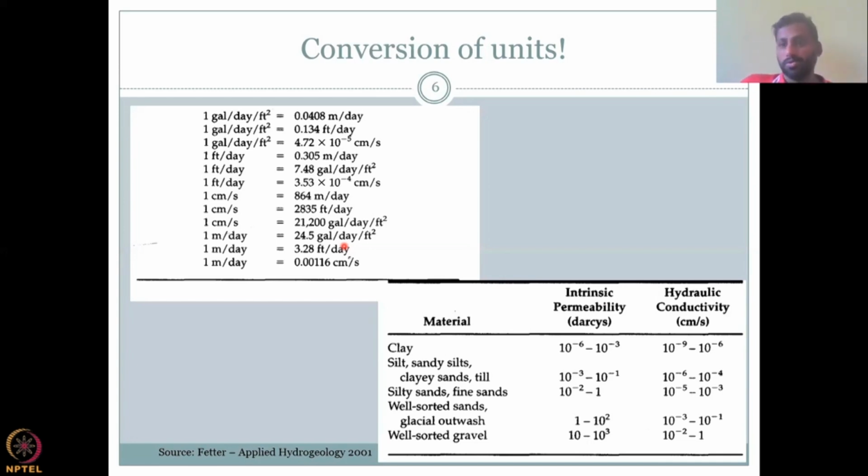And if they say clay, then you would understand that groundwater recharge would take a long time. We'll have some examples in the next class. So moving on, silt and sandy silts, the mixture of clay, sand, and particles, have a slightly reduced hydraulic conductivity, or a higher hydraulic conductivity, because sand can actually improve the hydraulic conductivity. So then when you go to silty sand and fine sand, you have more hydraulic conductivity. So we're going in increasing hydraulic conductivity.